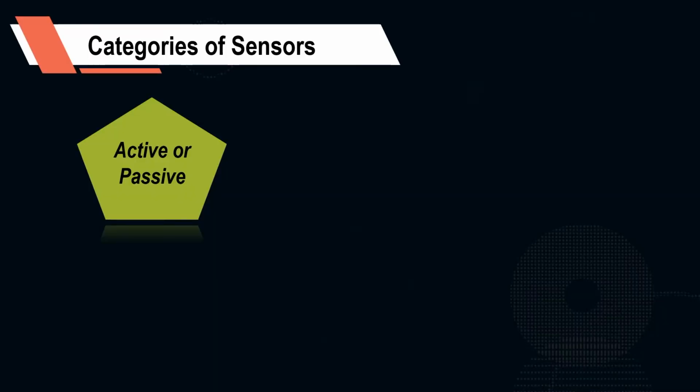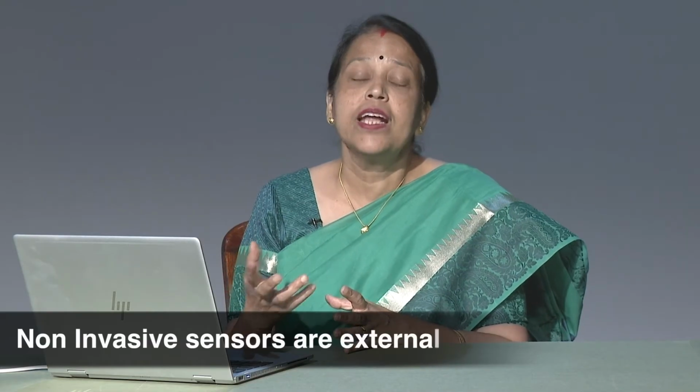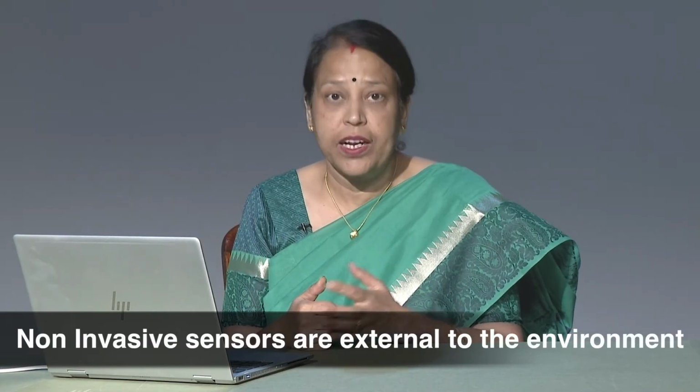The next category is invasive and non-invasive. Invasive sensors are part of the environment, whereas non-invasive sensors are external to the environment. For example, there is a pipe and within that pipe there is some fluid. Now, if we put the sensor inside the fluid, that is an invasive sensor. And if we put some sensors, for example optical sensors, on the outside of the pipe, then that sensor is known as a non-invasive sensor.